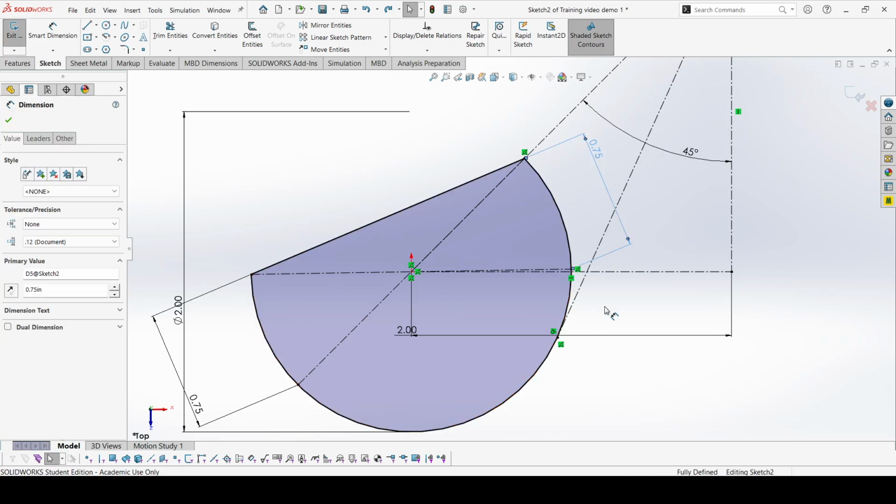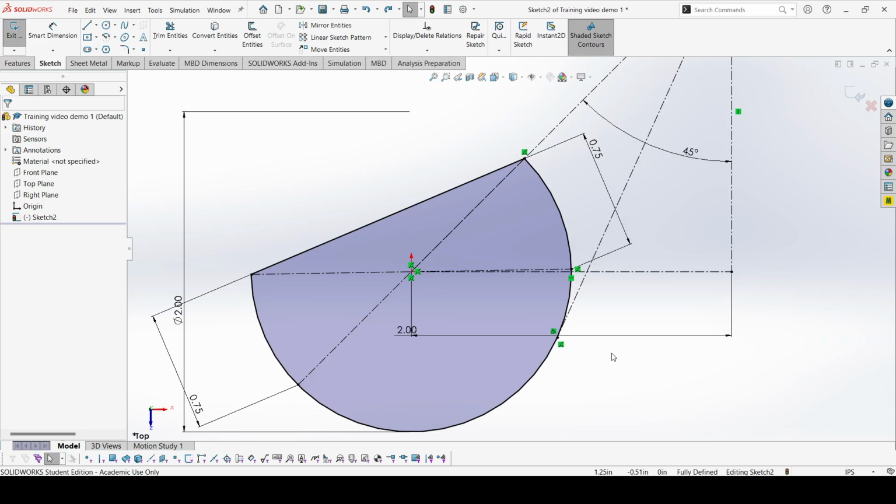Selected contours is the bane of my existence, to put it shortly. It is not good. If we change the sketch behind a cut extrude or extrude, it will not update unless we manually select each contour. It's not fun, especially if you have a lot of holes.